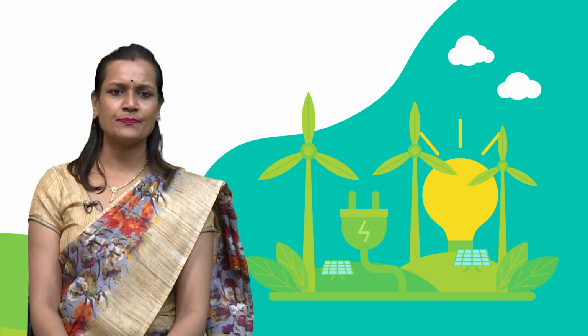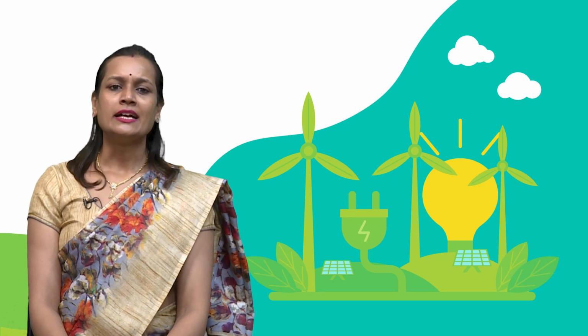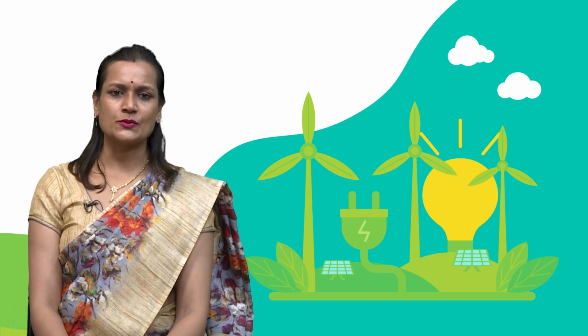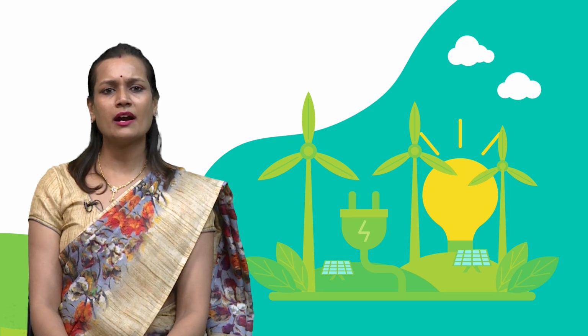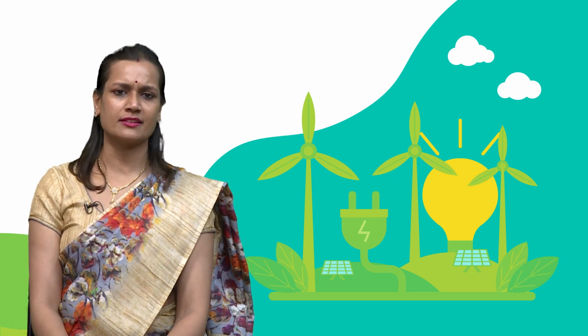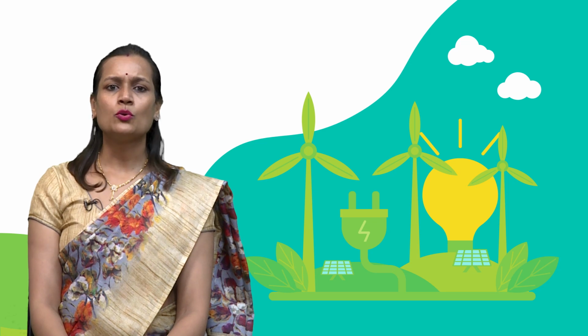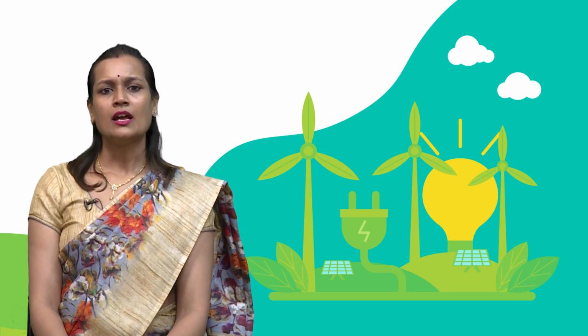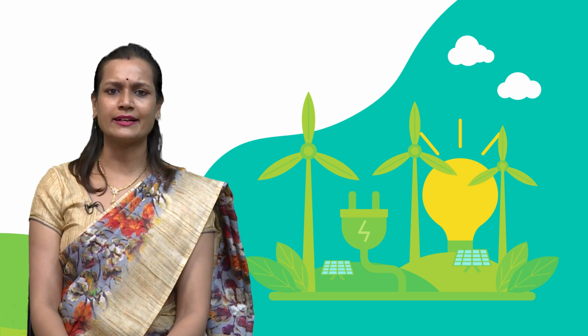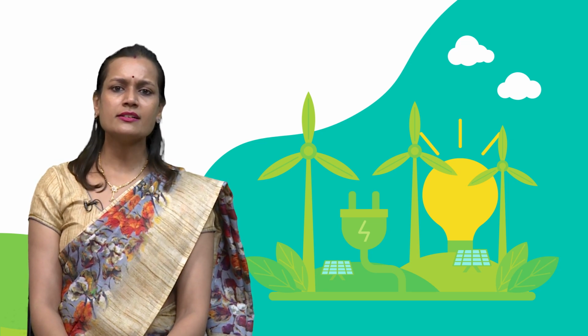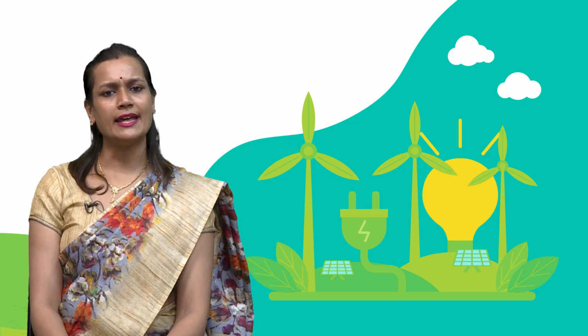As the tide comes in and goes out, the water flows over the tidal turbines. The movement of water causes the turbines to rotate. Some tidal power plants use vertical axis turbines while others use horizontal axis turbines, similar in design to underwater wind turbines. The rotation of the tidal turbines drives generators, which are typically located inside a housing or a nacelle attached to the turbine. The generators convert the mechanical energy produced by the rotating turbines into electrical energy.